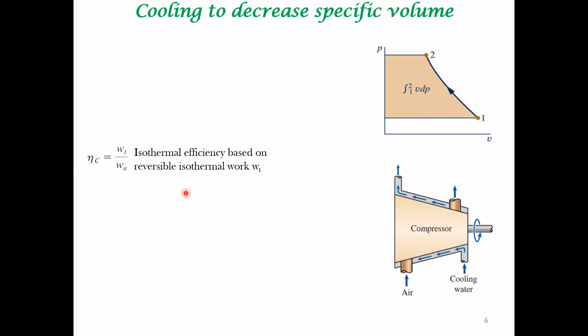Because of the importance of specific volume, we saw in the last lecture why you need to keep the specific volume low if you want to incorporate less work. So it's the other limit. In a work generating device, for example a turbine, you want to keep the specific volume high. However, for a system wherein work is incorporated, you want to keep the specific volume low.